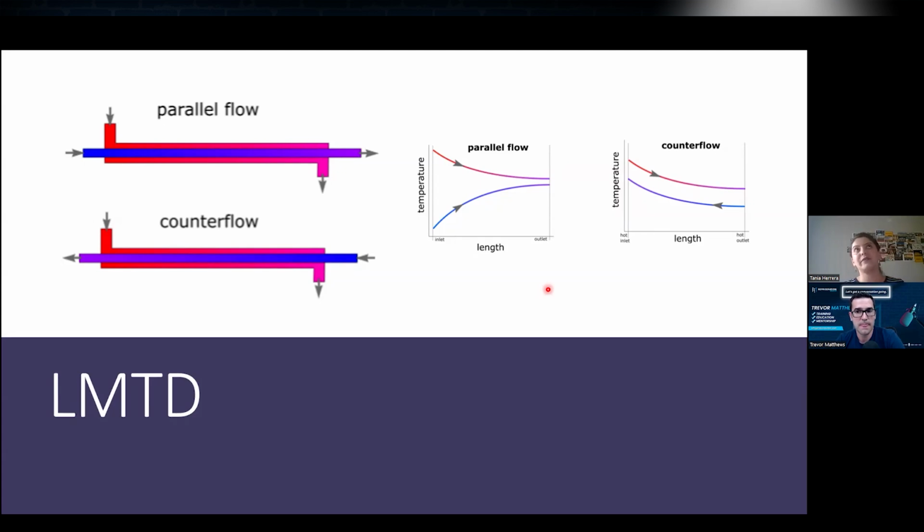But for instance, I have seen them in some heat exchangers for ammonia, because I read a study and it said that due to the physical properties of the ammonia, this is direct expansion. For this particular application, it was better to consider parallel flow, because they also have to consider the superheating circuit. Well, no, it's not a separate circuit, but we have to consider the superheating part on your heat exchanger. Yeah, exactly. That's awesome.